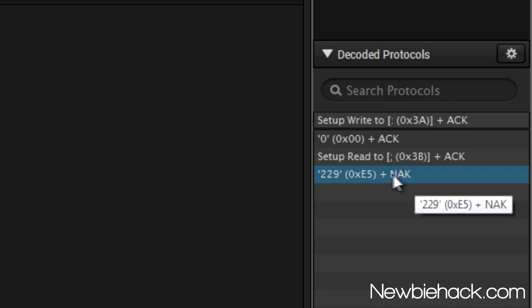And you can see that we also sent a NAC, so the instruction will be completed or ended. If we put an ACK here and we didn't put a stop, I'm not really sure, it may make a difference. I don't know if there is an EEPROM on the ADXL, but I have a feeling that there may be, because if you unplug it then plug it back in, it may still be waiting for another read.